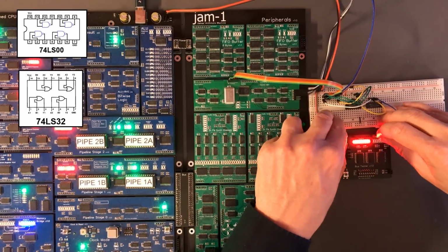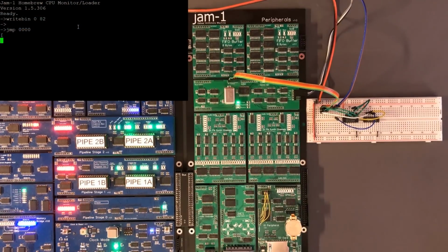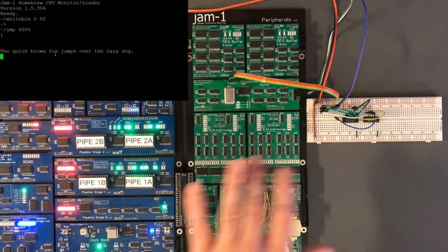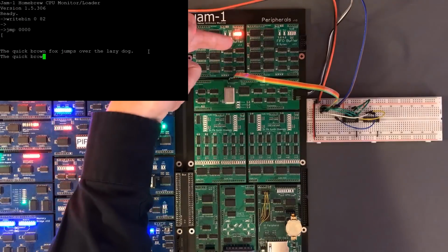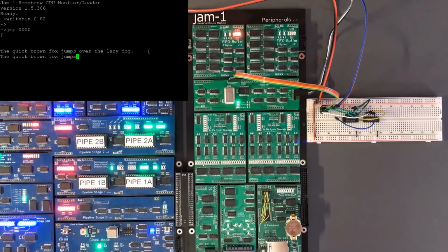And all we actually need to do is output that on the clear to send line. Now that always worked at full speed, but now we drop it down to trace mode where the CPU is running at a very slow speed and it's not able to keep up with the UART. Now we can see the buffer is pretty much switching between 6 and 7 bytes in it. And that message is received correctly.